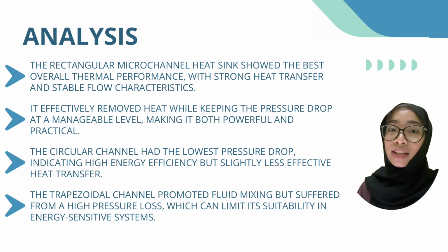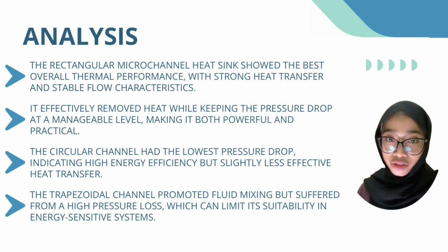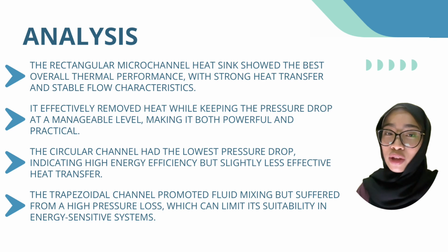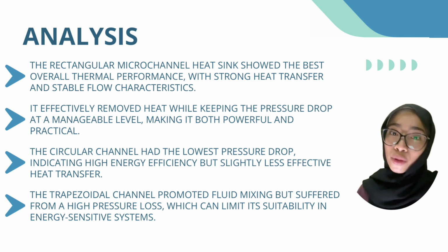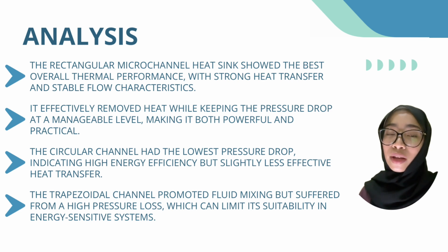The circular channel had a very low pressure drop, which is good, but it wasn't as strong in heat transfer. And lastly, the trapezoidal channel helped mix the fluid well, but caused a lot of pressure loss, which isn't ideal for saving energy. So when we look at the factors, which are cooling, flow, and energy use, the rectangular shape was the most balanced and reliable option.